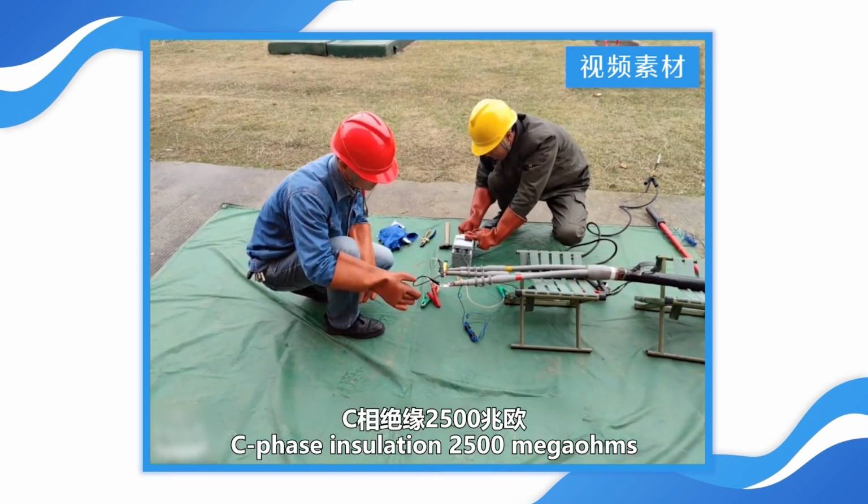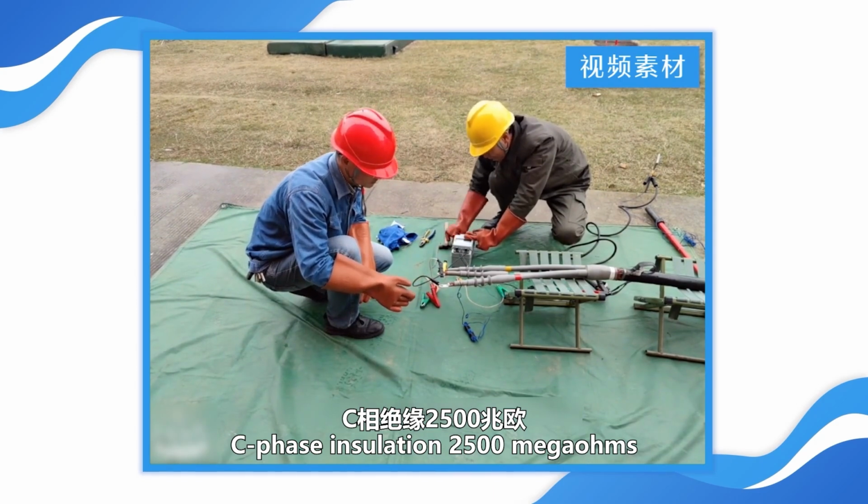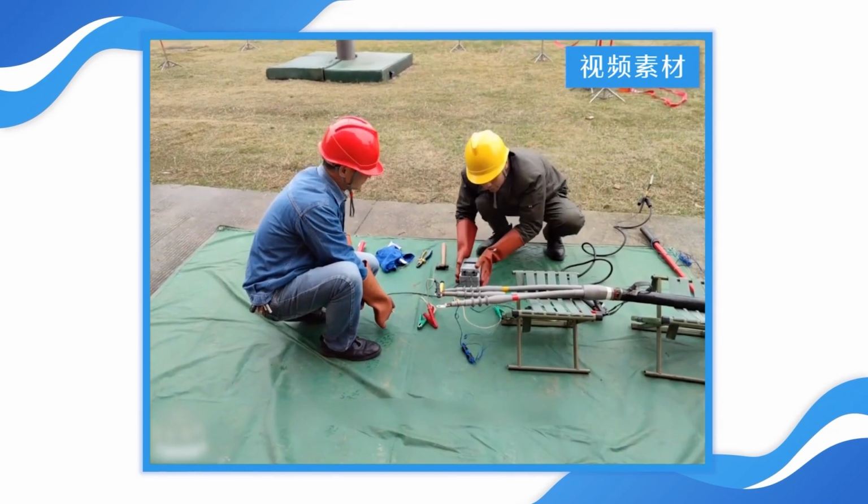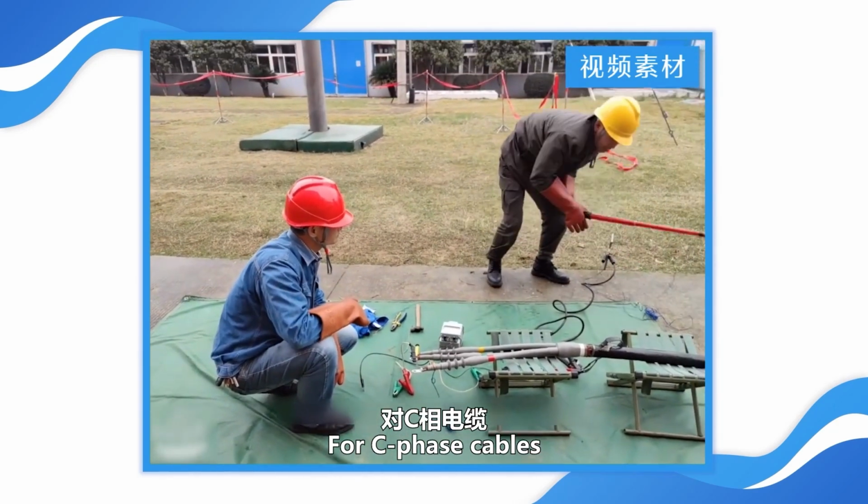C-phase insulation 2500 megohms. Remove the lead wire for the C-phase cable.